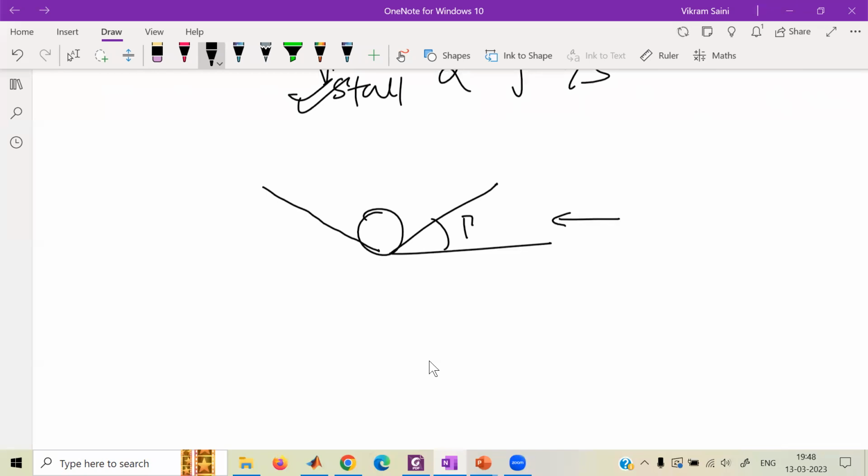So one of the components of this side wind is directly going normal to the wing, and this normal component of the wind to the plane of the wing increases the angle of attack on the downgoing wing, and decreases the angle of attack on the wing that is going up. That change in angle of attack, delta alpha, is quantified as tau times beta.